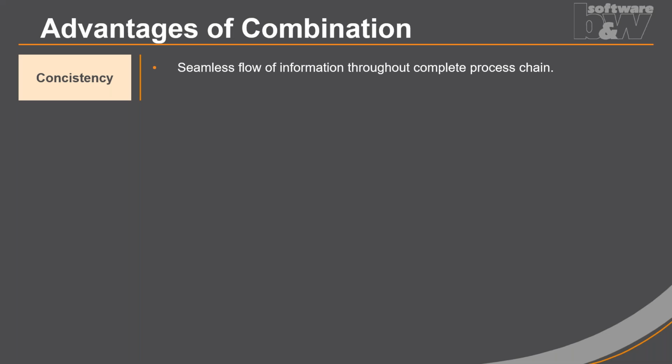In case colors don't transfer through any kind of gate, like a merge feature or a split, in most cases, parameters do flow through this gate. And you later can use the parameter to set the colors, or vice versa. If parameters don't get through, like a step export and import, then you can use the color to set the parameters.